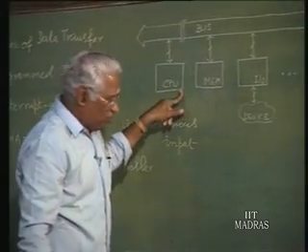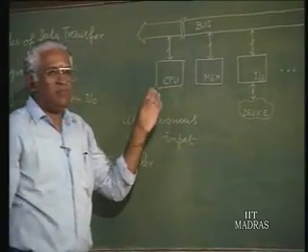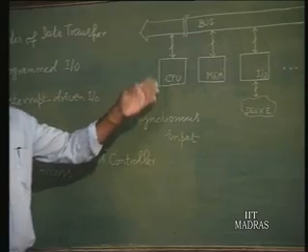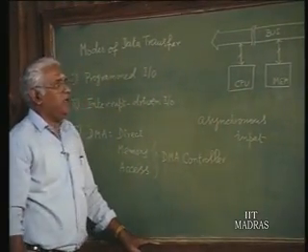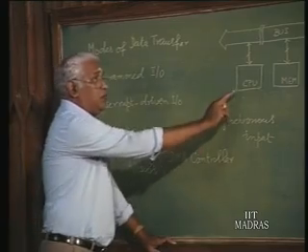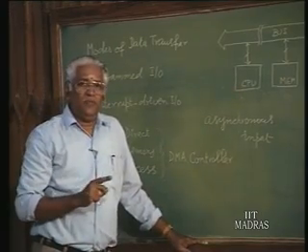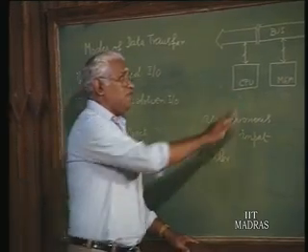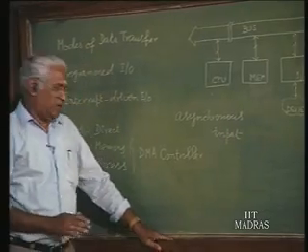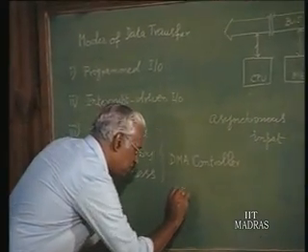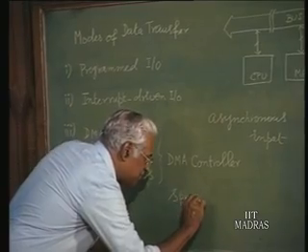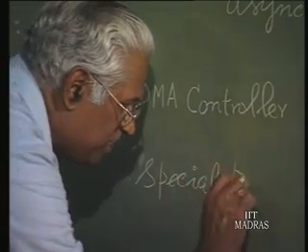Earlier the CPU was involved, now the CPU is cut off from the bus. Now instead the DMA controller will take over and it is going to play the same role as the CPU, but the CPU is a very general purpose processor, whereas a DMA controller is a special purpose processor. This is specifically for a special purpose, and what is that purpose?